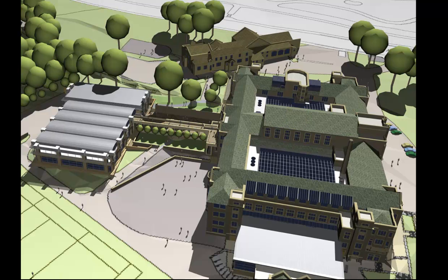Worth mentioning as well that the existing buildings in this model and also the one for the technical college were not generated from drawings, they were generated from photographs. Photographs that were taken and then manipulated in PaintShop Pro. Photoshop would work equally well. And then inserted into a layer in MicroGDS and traced over to create the shapes that were then extruded into 3D.